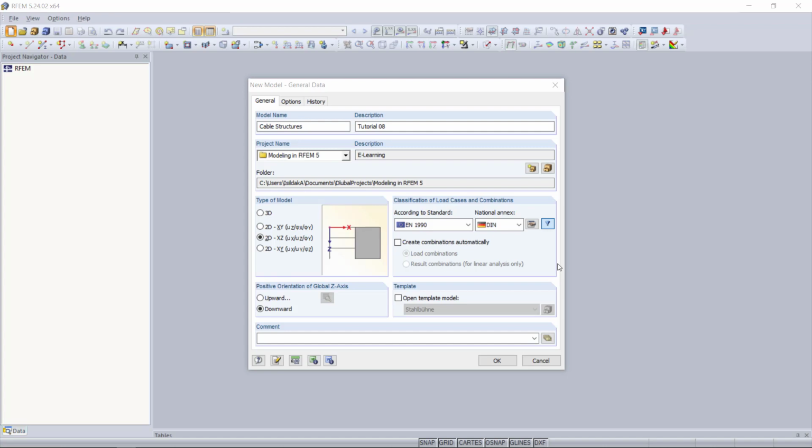Since this is an iterative calculation, the results are reached by an approximation, and with an approximation, the most exact solution can be found. But this also involves the largest calculation effort. So if you have, for example, bracings, it's better to choose tension as member type instead of a cable. Apart from that, we also have the add-on module RF-FORM-FINDING, and with that we can set, for example, the cable absolute sag, which we will do for our example later. So much for some theoretical aspects, and now we will start modeling our structure.